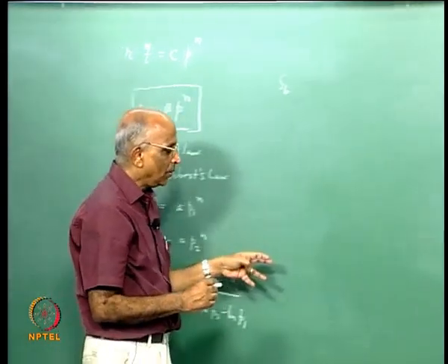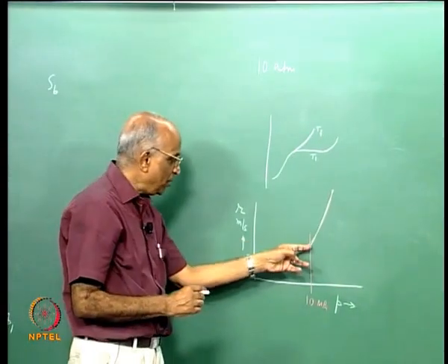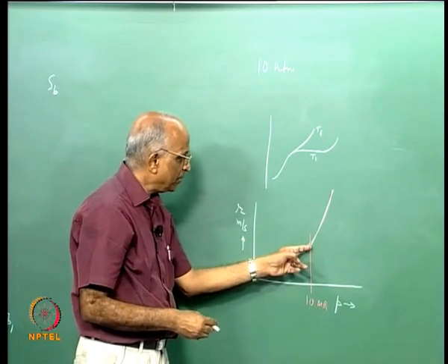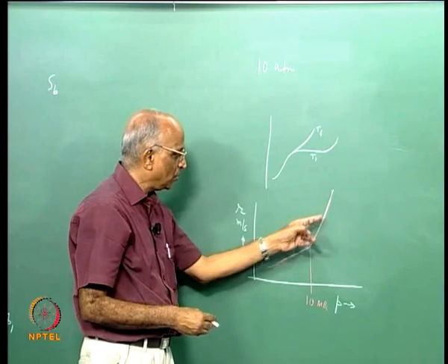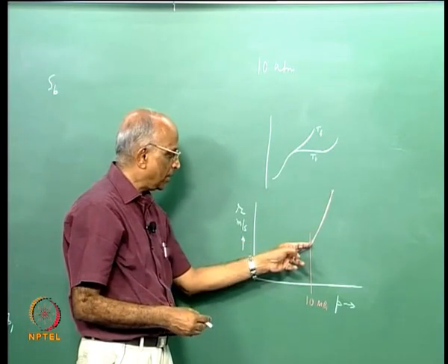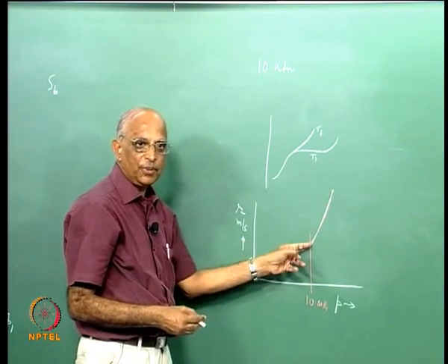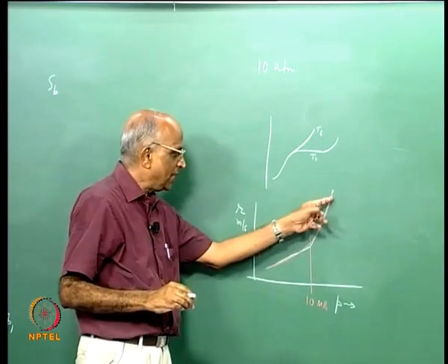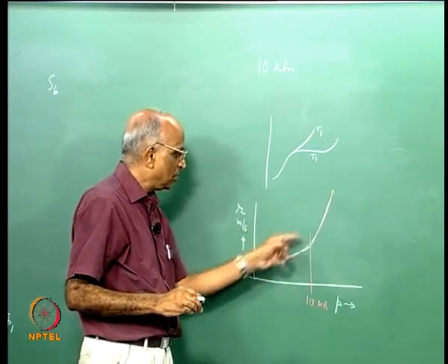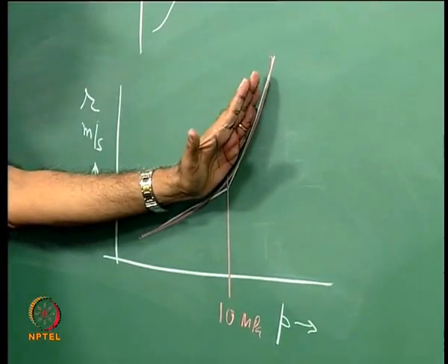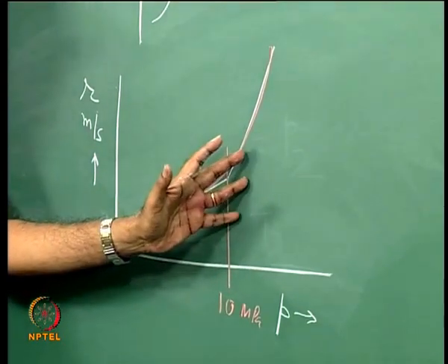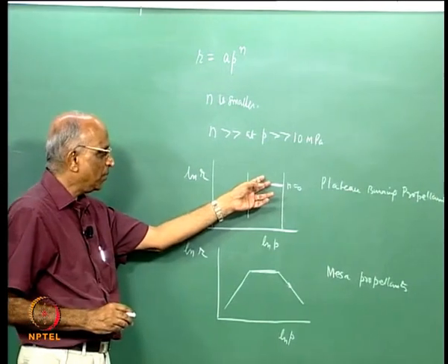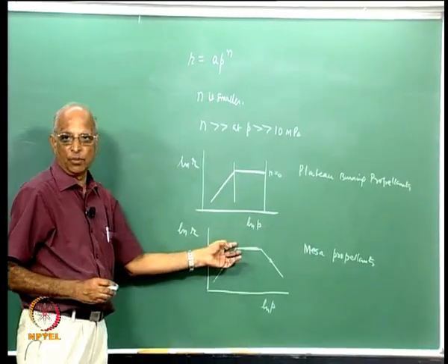Thereafter, we said that at high pressures the reactions happen directly, that means instead of having a dark zone you do not have that. That means at high pressure the temperature increases from surface temperature directly to the flame temperature, more heat gets conducted, therefore n is higher, so you have a small n followed by a large n for double base propellants. Then we said, if I add some salts I could have a plateau burning propellant or a mesa burning propellant.